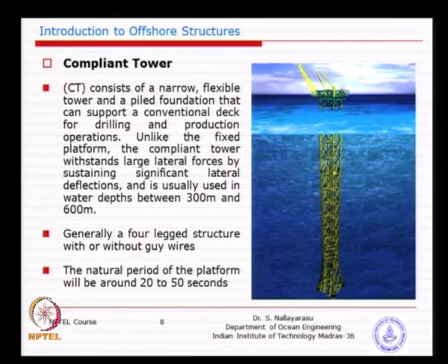And the natural period is very large, because of the slenderness, it just goes beyond the wave periods. That is how you assign the structural strength in such a way that you do not go into a lock-in period of say 10 seconds, 15 seconds, which becomes a potential problem. Resonance will create a lot of trouble.